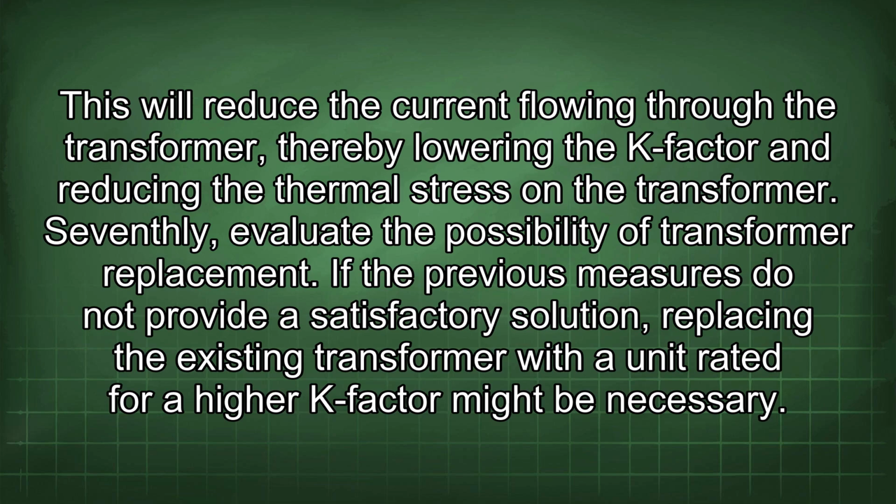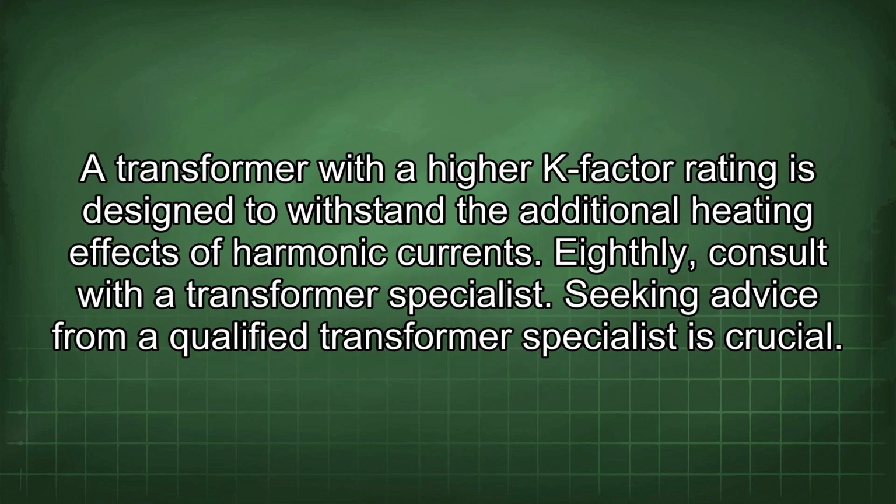Seventhly, evaluate the possibility of transformer replacement. If the previous measures do not provide a satisfactory solution, replacing the existing transformer with a unit rated for a higher K-factor might be necessary. A transformer with a higher K-factor rating is designed to withstand the additional heating effects of harmonic currents.